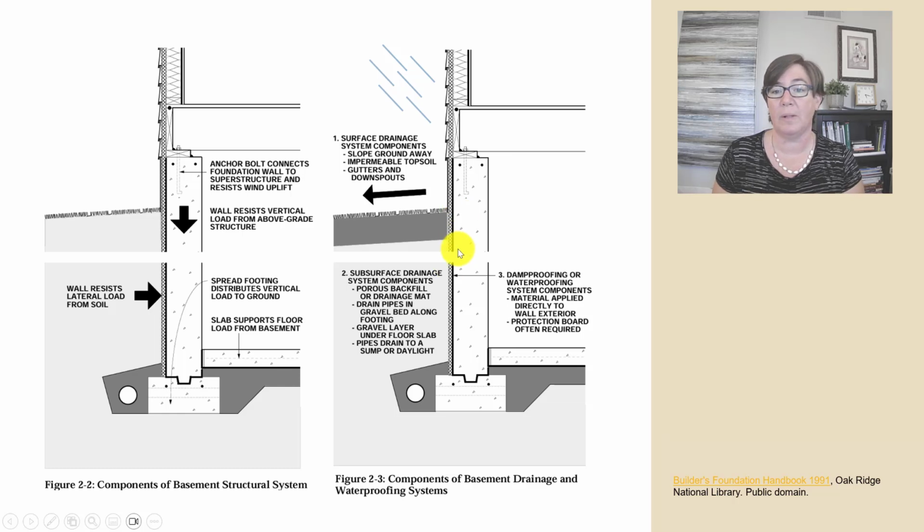And so we will have a waterproofing system along this outer edge. And that's going to drain the water down, and finally into, this is going to be an area of gravel down in here with a perforated drainage pipe that'll take that water away from your foundation.